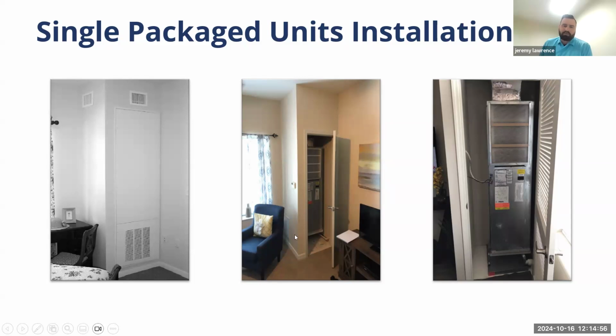In this picture, the return air is on the side of the unit, but more often in Ontario, what we're seeing is they're using the bulkhead around the supply duct as a return chase and being able to put the return ducts back into the bedrooms where we want them, further away from the unit. Obviously, it helps with the comfort level of getting the return air further away from the unit. It also does help with wind noise, to keep them quiet.